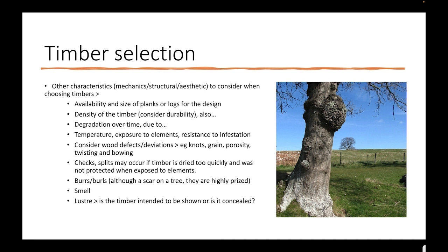So the availability and size of planks or logs for the particular design that you're specifying, the density of the timber, so think about how durable you need it to be. Degradation over time and changes in color quality might be a factor for your consideration. What sort of temperature does the timber need to work within? Its exposure to the elements, resistance to infestation, these are all important considerations. Think about whether you need the wood to show grainy features or knots, its porosity, whether it's susceptible to twisting and bowing.